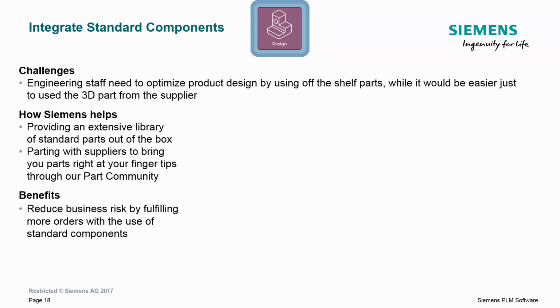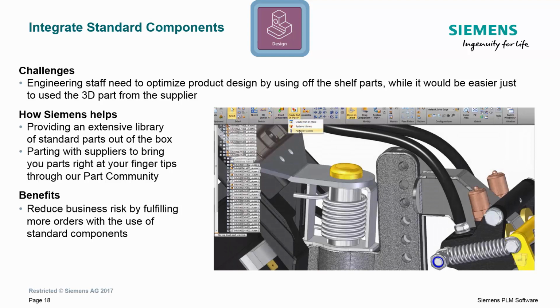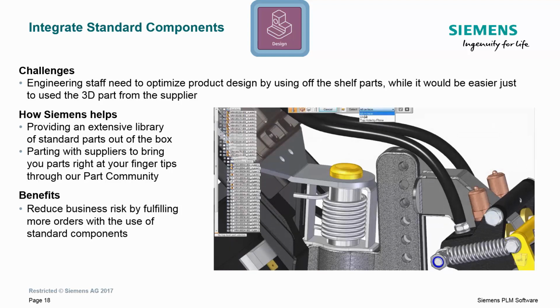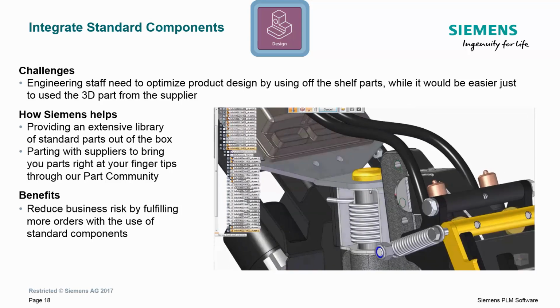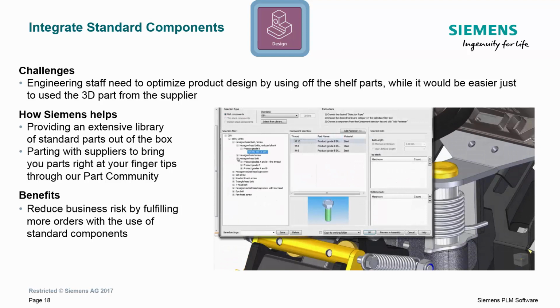As is true with most assembly designs, there needs to be fasteners to bolt, screw, or pin components together. Solid Edge provides an extensive library of fastener components based on any common standard and automates their creation and placement. This automation saves designers lots of time and headache not having to model and place the fastener stacks individually.